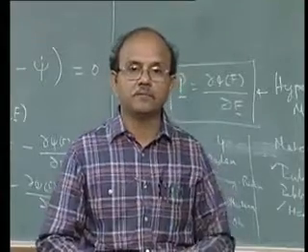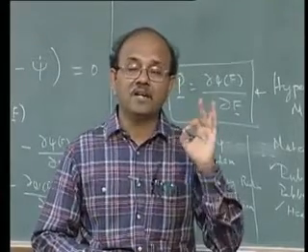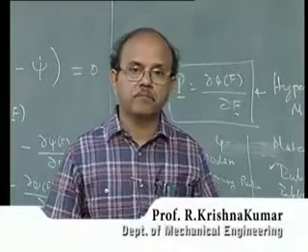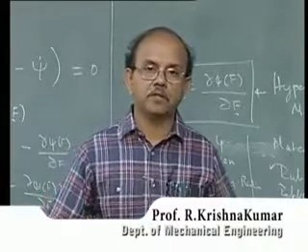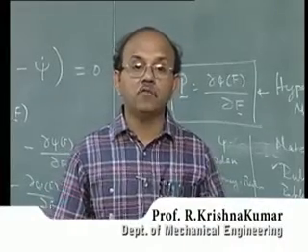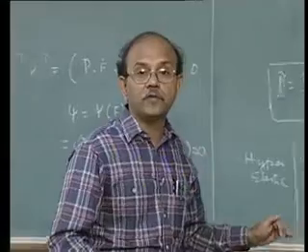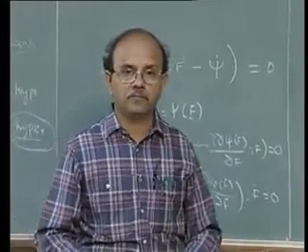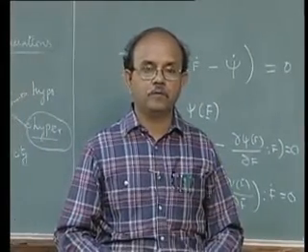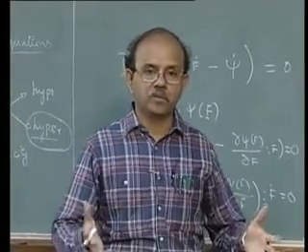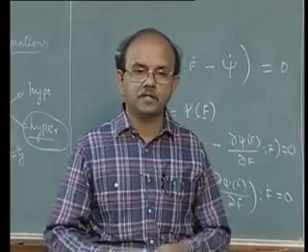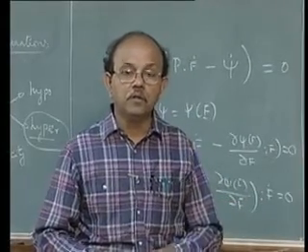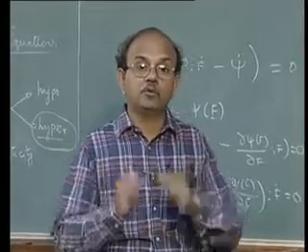You have to really understand how it behaves. Maybe go back and look at the literature, and you find that people have put down Yeoh's model specifically with a purpose in mind. Yeoh put this down, if I remember right, in the early 90s. So then you go and apply Yeoh's model.